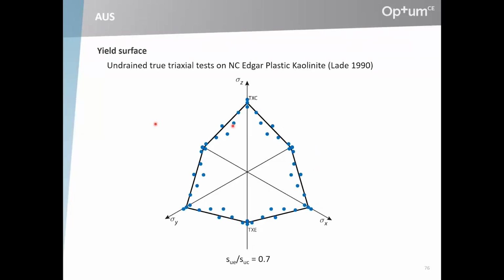And so the predictions, or the fits you would get with this NGI ADP model, would be less than optimal. This is the generalized Tresca fit, and then the NGI ADP fit to the same data. So yes, you match things in extension and compression, but everywhere else it's a bit random what you get.